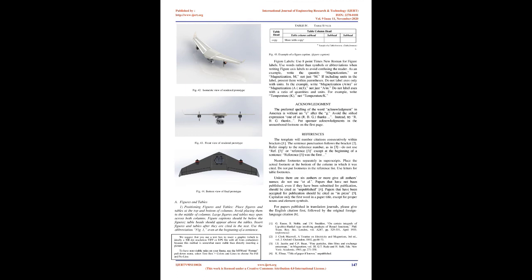Loading conditions. A 75 N force is applied on the other end in the downward direction, making it a cantilever beam. This is to simulate 3 g forces experienced by the spar while supporting the flying wing during takeoff, cruising, touchdown and underwater traversal. The weight of the flying wing is 1 kilogram, 10 N. Tables 1, 2 and 3 specify the material properties, design dimensions, and mesh properties respectively.